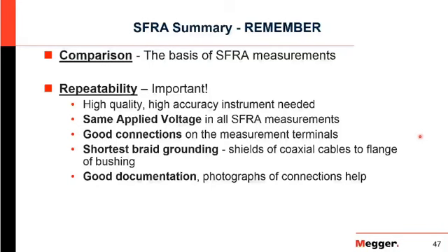And then also just good documentation. Make sure you note the tap position. Make sure you note if you didn't have oil or you had test bushings in there. You want to make sure all that's noted, so if there is a difference, you can see, no, we actually changed the parameters here. We're not comparing apples to apples, so you're not throwing yourself off there. So looking at this, as I said, we really want comparison and repeatable results.